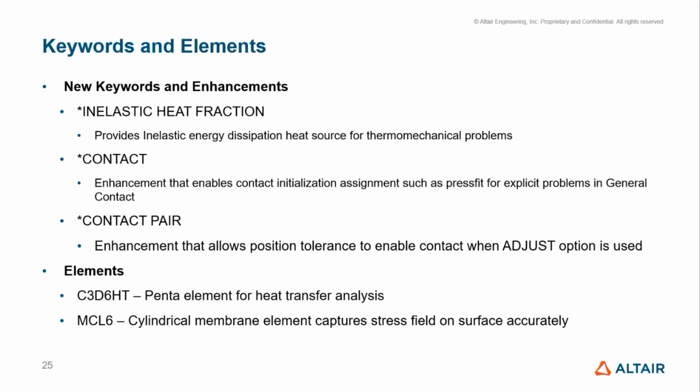This is an enhancement that came in Abaqus 2022, and we have incorporated it in our current version, along with two new elements: a penta element for heat transfer analysis, and a membrane element to capture the stress field required for fatigue analysis. You need to use these membrane elements to capture the surface-level stresses. For further post processing in fatigue analysis, you would want to know the exact surface stresses, especially when you are using 3D elements. The extrapolation might cause some kind of error. So you use the surface elements to capture accurate surface stresses to further post process with fatigue. That particular element is also supported.